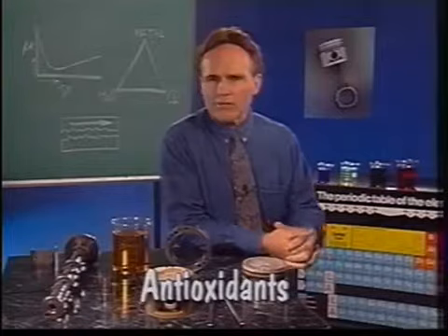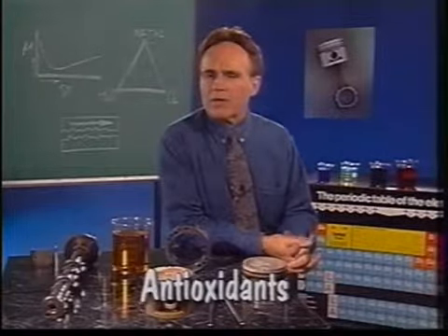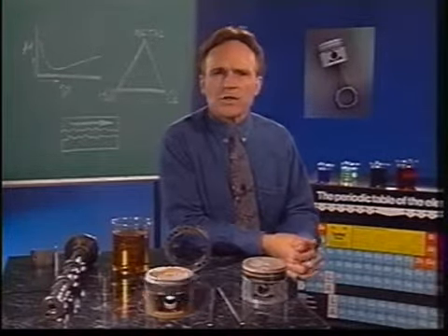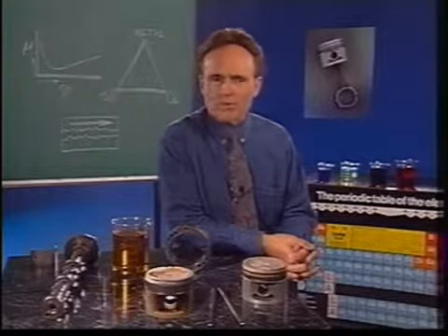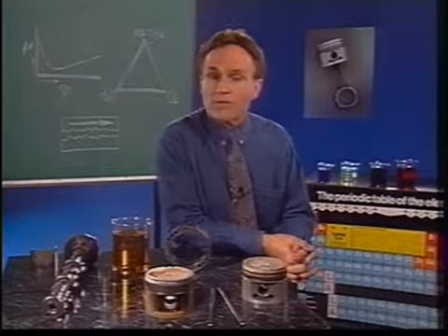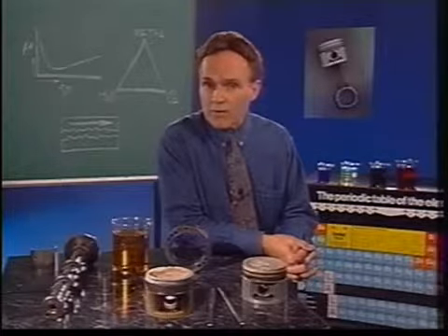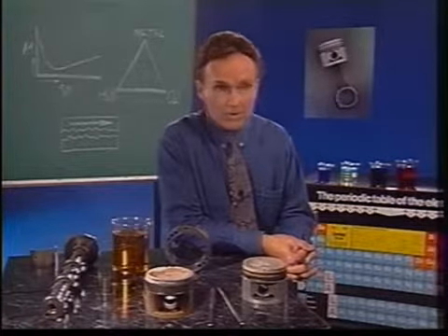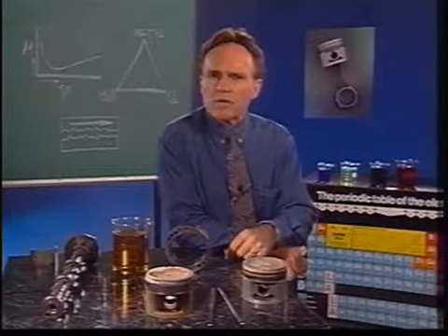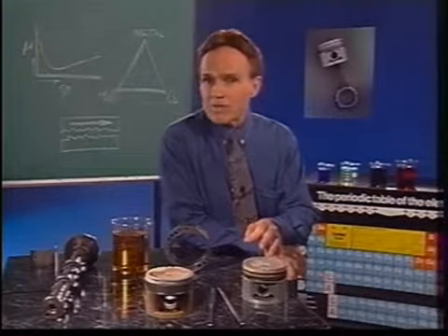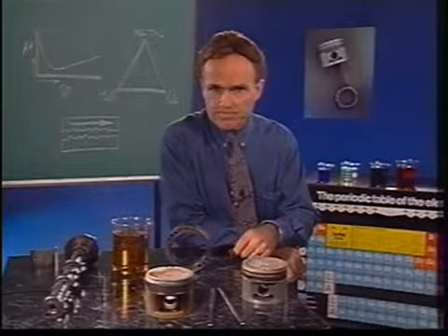Antioxidants minimize lubricant thickening and degradation caused when oxygen reacts with the churning lubricant at high temperatures in engines, transmissions, and gearboxes. As a rule of thumb, for every 10 degrees centigrade increase in operating temperature, the oxidation rate of an unprotected lubricant almost doubles. Antioxidants work by either reacting with unstable oxidation products or by decomposing peroxides in the oil.